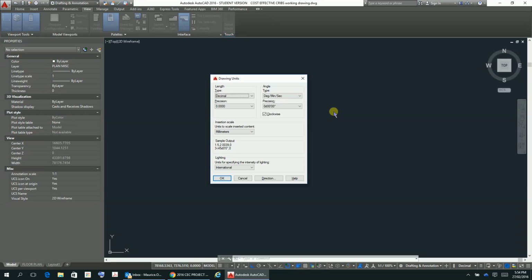So in this instance, for architects and mechanical engineers, where we're dealing with smaller objects, usually sub-meter, or even sub-20 meter, sub-30 meters perhaps, it is probably prudent to keep in millimeters, and then AutoCAD stays relatively true for you. Certainly decimals are the option. There are other options in there: engineering, fractional, scientific, and architectural. I would stay away from the architectural, just leave it at decimals.